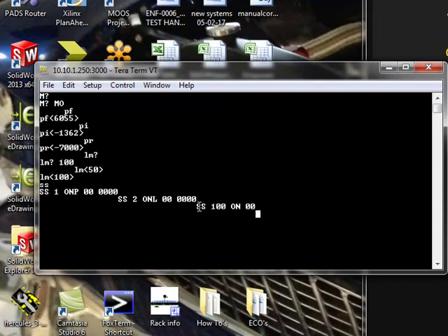The top level system status is reflected by the show status at index 100. Our philosophy here is that the protections that are done at the top level are set tighter than the ones that would be found inside the booster.